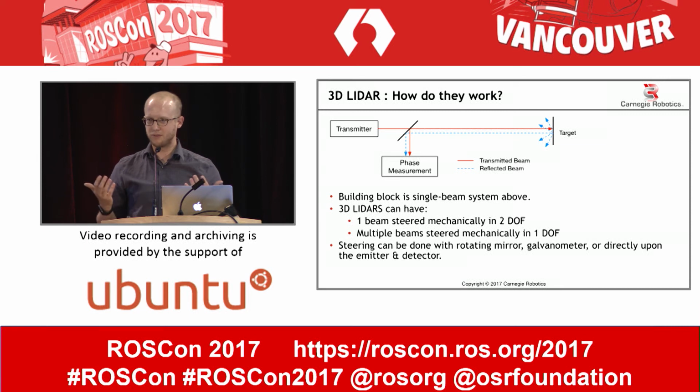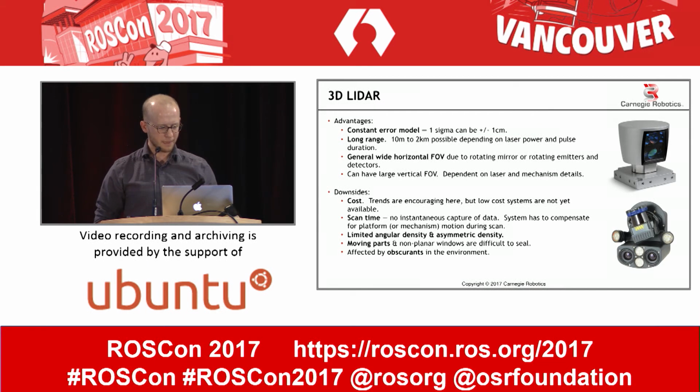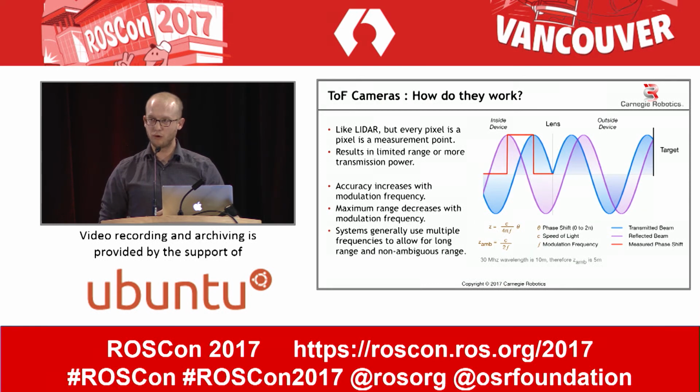And at some point, hopefully in the near future, solid-state LiDAR will be a more realizable and purchasable product. We're not quite there yet, but that will be an exciting time when that happens. The really nice thing about LiDAR is it has a constant error model. Even at very long distances, the 1 sigma accuracies are very good. They can be very long-range sensors, but you have real limitations in data rate and in horizontal and vertical density, and depending on the task of your system, that may prevent or limit the use of 3D LiDAR, which is where 3D time-of-flight cameras and stereo cameras can sometimes be more effective.